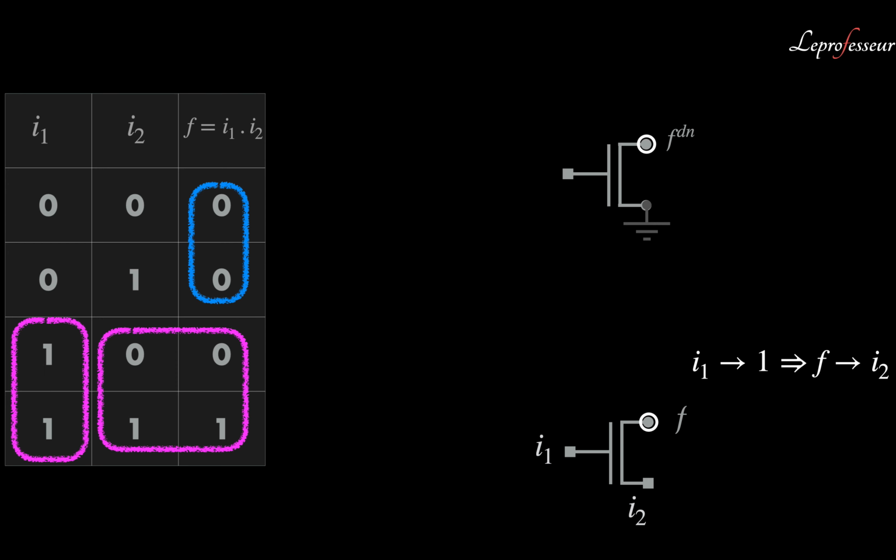So what we can say here is, what if we connect the gate of the NMOS with the inverted value of I1? That means we put an inverter and connect the inverted value to the gate of this transistor, and then we connect one of the terminals to the ground, then we will get a 0 value, which means that we are covering the above half.